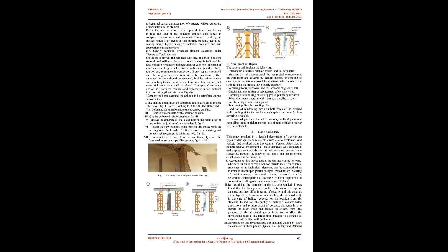B. Non-structural repair. The actions will include the following: patching up of defects such as cracks, and fall of plaster. Stitching of walls across cracks by using steel reinforcement on wall faces and covered by cement mortar, or grouting of cracks using cement or epoxy-like adhesive materials which are stronger than mortar and have tensile capacity.